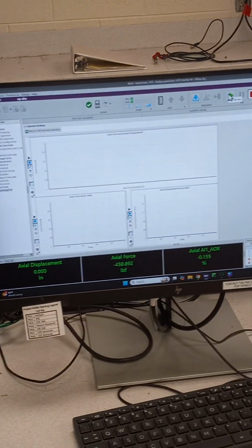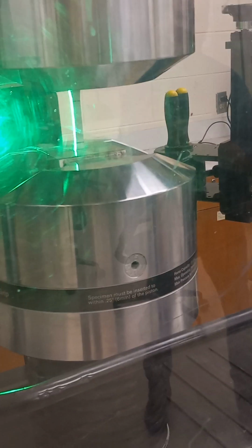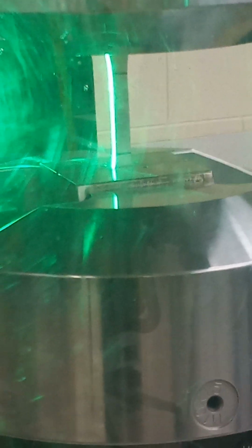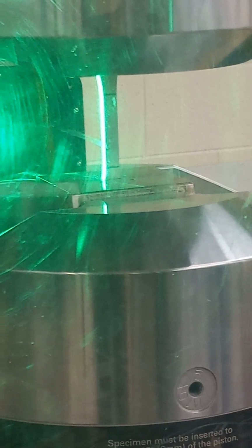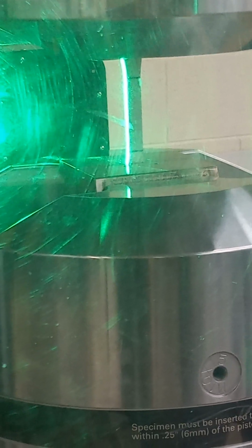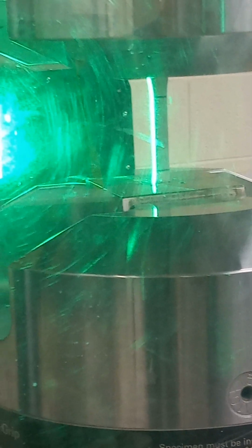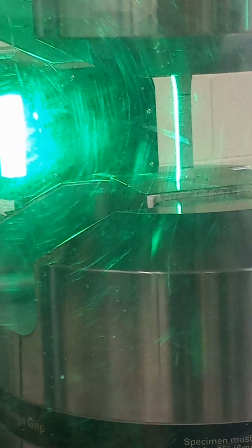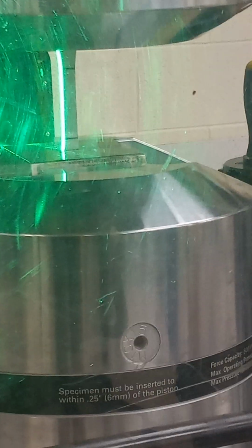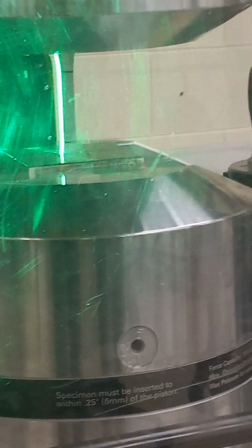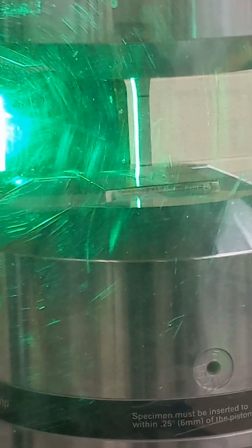Okay, go ahead and start whenever you're ready. We're gonna run it. I usually hover my mouse over one of the stop buttons so that I'm ready to hit it if something goes wrong. Okay, let's do it. I pressed it. So now you can see the data rolling in. It's pulling. This is good to watch while it's pulling. Watch your strain. Make sure it's moving. Strain is moving, and look at the force on it already. You can see it's plateauing. Oh yeah. It's trying to break.